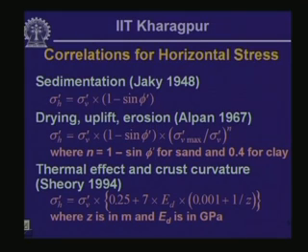Now if you have got unlithified sediments, freshly deposited unlithified sediments that has consolidated or that has stabilized under its own weight, in that case sigma h prime is going to be equal to sigma v prime multiplied by 1 minus sin phi prime, and this is the expression proposed originally by Jaky, and it actually works quite well in case of unlithified soils that are yet to get cemented and become rock like.